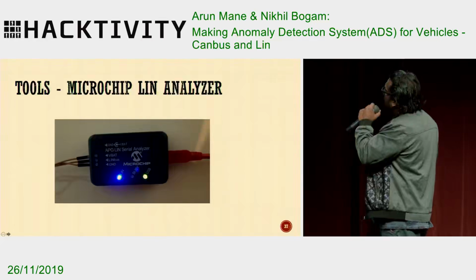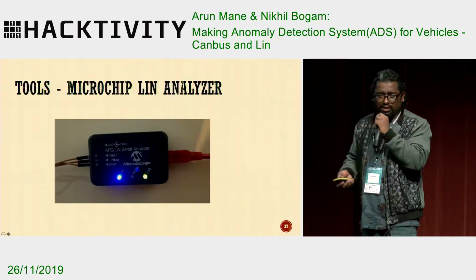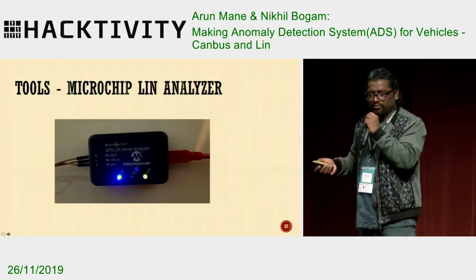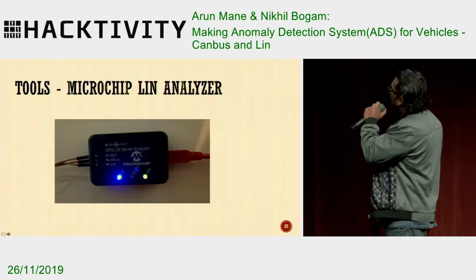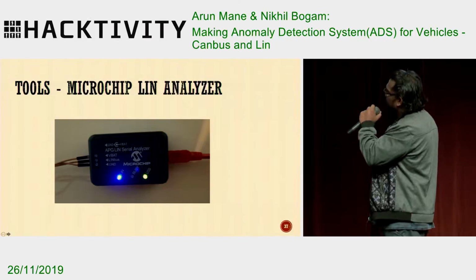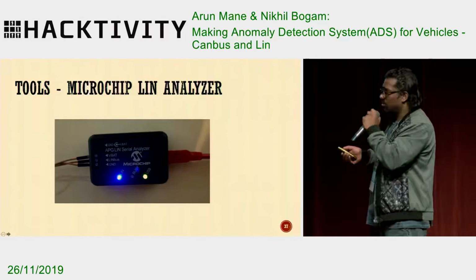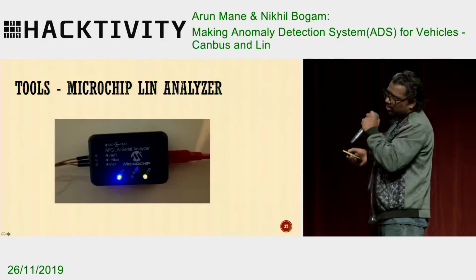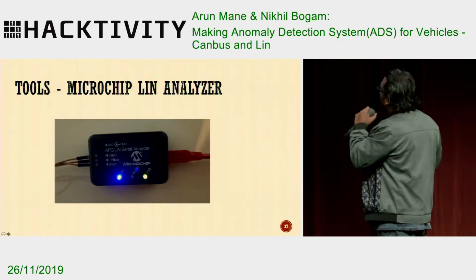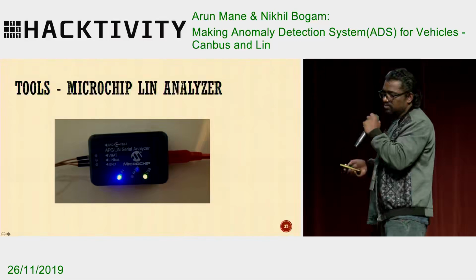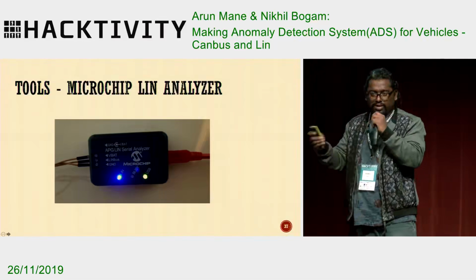For the LIN protocol, there are different kinds of vendors in the market as well. You can check Vector, and we can check Intrepid tools which support the LIN protocol as well. For very cheap things, it's cost effective. It comes at $25 to $30, and the software is also open source, with free editions. So we call it a LIN serial analyzer. So you can intercept all the communications of the LIN protocol, and you can do a ton of things.